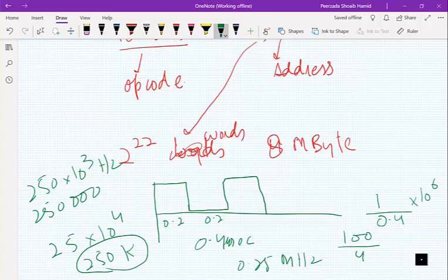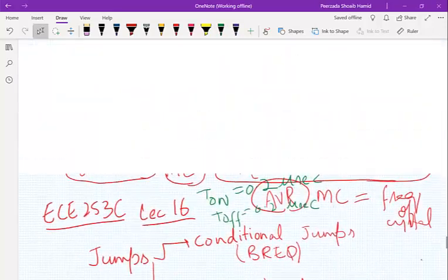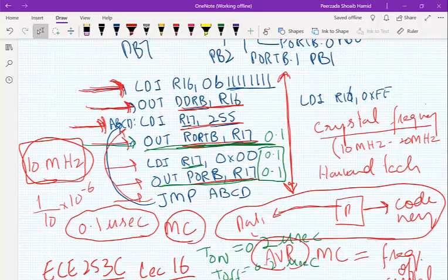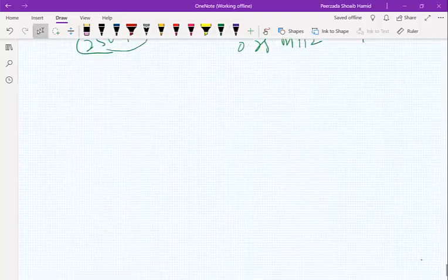So what we normally do if we had this kind of objective in mind, that we have to turn LEDs on and off for some function, what can we realistically do? We need to incorporate delay between instructions. For example, after turning the LED on, we might incorporate a particular delay here, and after turning them off, we again may incorporate a delay here. So, delay.